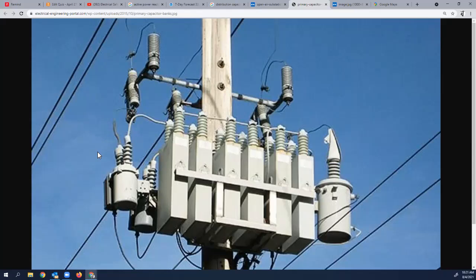Two, the other part of this: you see the wires coming out of the bottom. They're controlled. When SCADA sends a signal, this is the control part, the component that opens and closes. Obviously, I can't have a guy standing at the cutouts to open and close those switches. That's not going to work. So I put controls in a vacuum bottle. All those cables coming out of the bottom go down to the control panel and a radio, and these will automatically open and close when they receive a signal. So two main purposes: I can break and make loads inside of them, and they're automated. SCADA can control them.